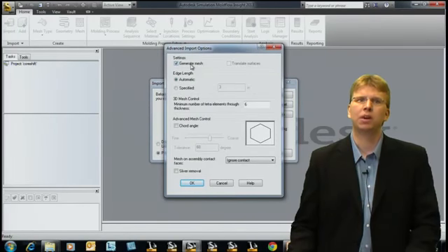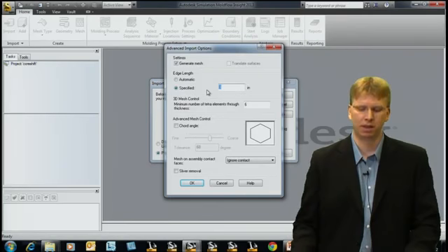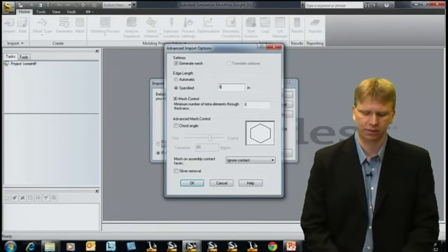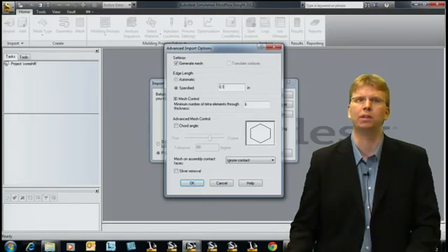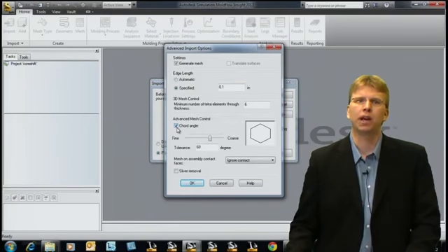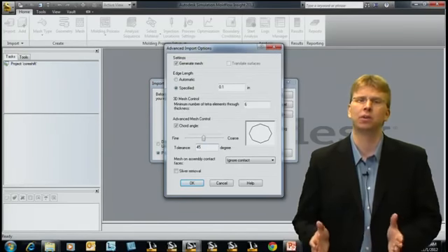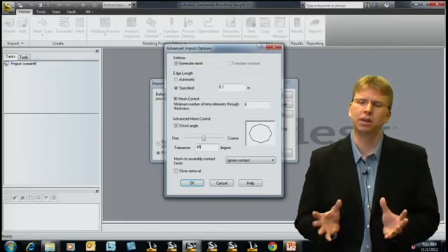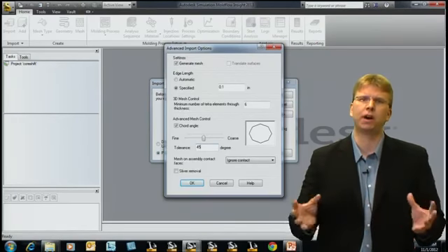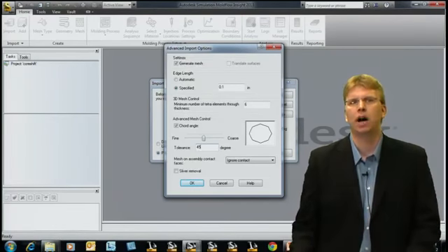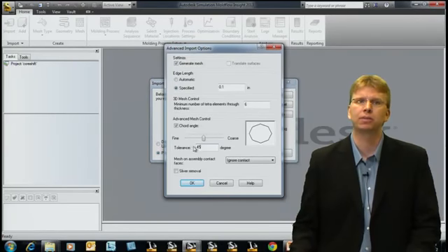When you go into the advanced option, we can generate the mesh, we can define edge lengths. I'm just going to make something that's relative, so I'm going to use a 0.1 inch mesh for our global edge length. And I'm also going to turn on chord height. What this will do is make it so that our cylindrical surfaces have more facets, or essentially more detail, to give that concentricity of the model more facets or more mesh.